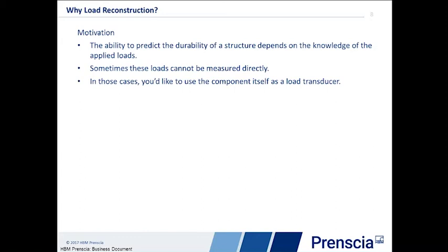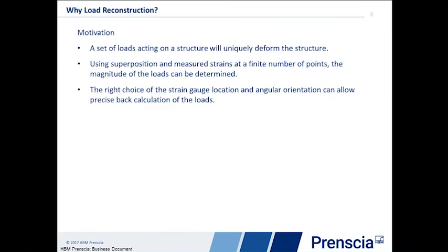So if I want to know the loads on a particular component, I may end up changing the load path, trying to put in things like force transducers into the structure. We're going to look at trying to turn the component we're interested in into its own force transducer.